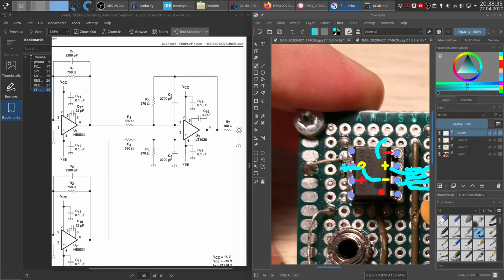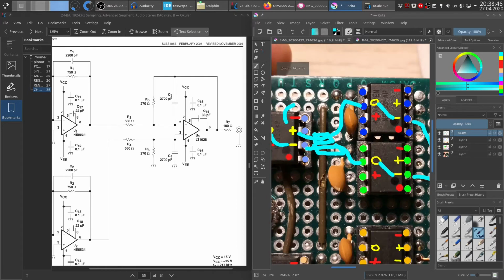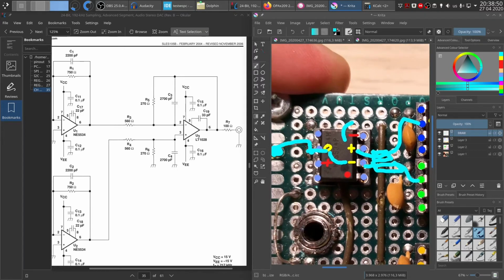Also it goes on this line, so this line can be approached via oscilloscope probe, so it can be easy to probe the output directly. Again, you could also use the differential signals over here on the output and have differential output, which is much more preferred because it's less prone to noise. Because when you do this differential to single-ended, as we discussed in the previous video, we reduce the common mode noise.